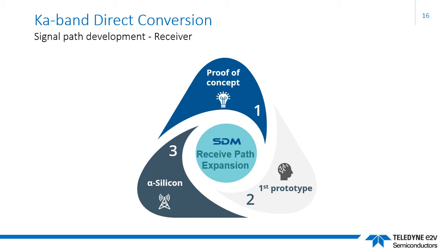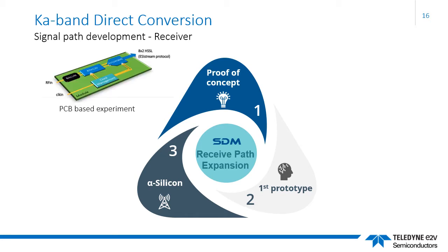Step 1 was to establish a proof of concept sampling system pairing a 20 GHz plus track and hold amplifier with the existing AQ600. The target of this work was to validate whether the track and hold and ADC combination could achieve viable spurious free dynamic ranges beyond the raw bandwidth of the ADC.